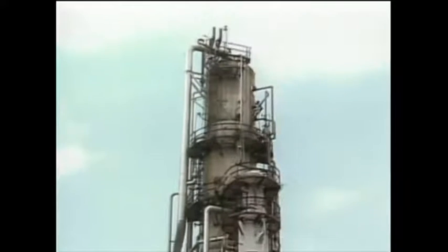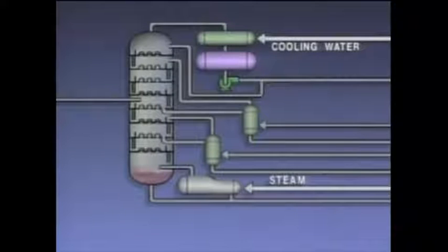The multi-draw tower illustrated here is used to separate a mixture into four products. Each product may be made up of one or more substances. The tower has four draw-off lines located at different levels. The draw-off lines provide a means for removing the products of the distillation. We'll number the products 1 through 4 to identify them. The illustration also shows two devices called strippers or side stream strippers, a condenser, a receiver, and a reboiler.